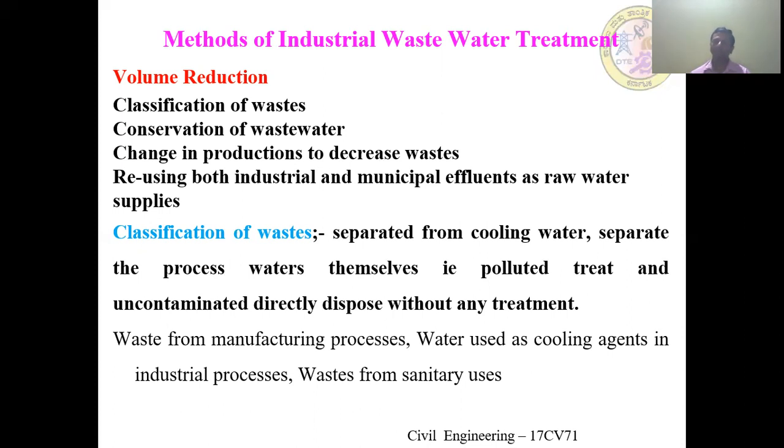It will be useful for different types of treatment also. And if the water from washing of raw materials contains only inorganic materials, it can go directly to a sedimentation tank. So the clear water can be used for some other purpose.